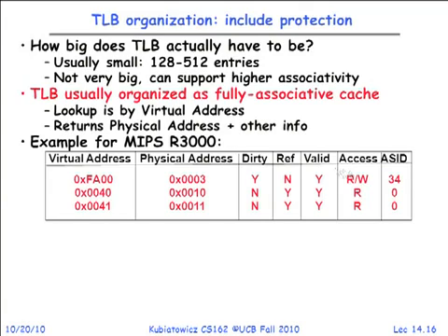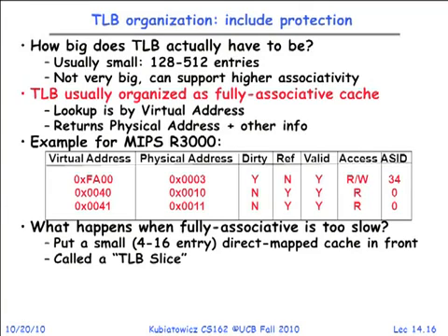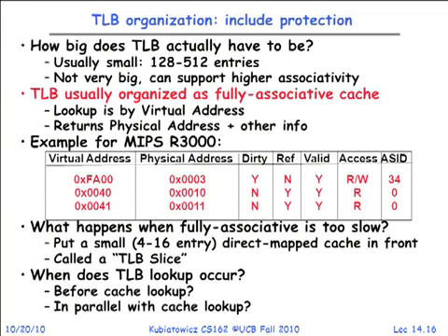And so now fully associative is slower. What happens if that's too slow? Then you put your TLB slice on top. Questions? Yeah. How can fully associative be slow if it's parallel? So why is fully associative slow? Because there's more stuff. It's bigger, and so bigger is slower. You've got higher capacitance. Signal time? Yep, the signal time is larger. This is unfortunate physics. If you take a hardware class, you start learning that bigger is slower, and that's almost always true.